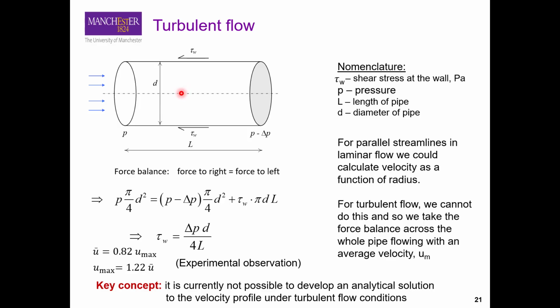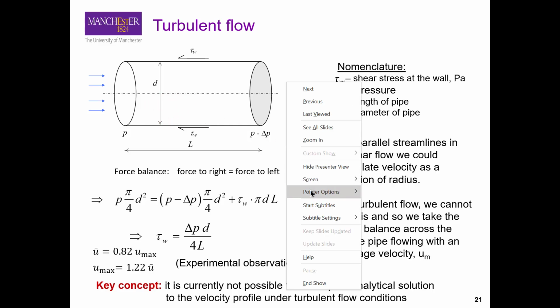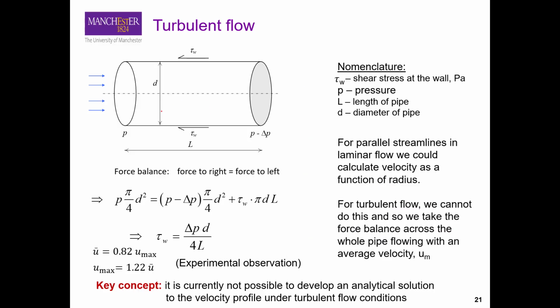While for the case of turbulent flow, as you remember from previous parts, there is a lot of intermixing, and as such, the velocity is changing from point to point. It means that if we assume a certain differential element here, it would be different from this differential element, and so with other elements. Okay, it means that we cannot really consider a differential element and then perform a force balance on that. But instead, for the turbulent flow, we perform a force balance on the overall system.